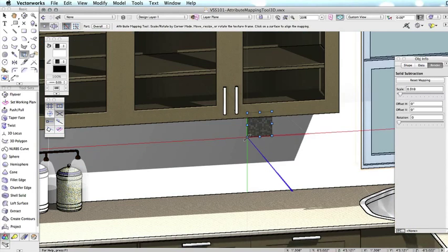Choose non-repeating or original repeat mode from the toolbar, as well as a scale rotate mode. In this example, we will choose non-repeating mode and scale rotate by corner. Notice the editing frame that is placed on the object. This means you are in 2D mapping mode. To switch to a 3D mapping mode, click on one of the 3 space axes, which are red, blue, or green lines. To switch back to a 2D mapping mode, click within the editing object.